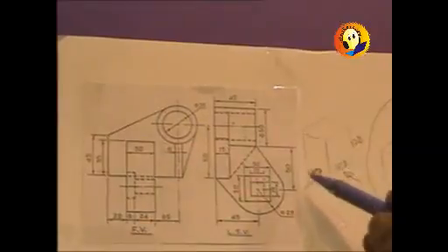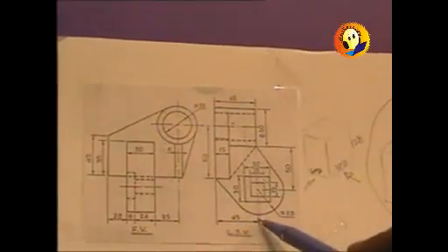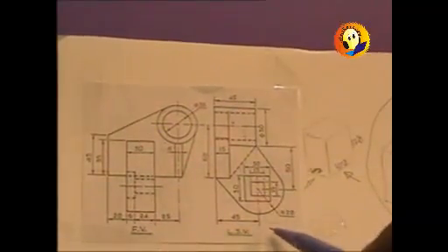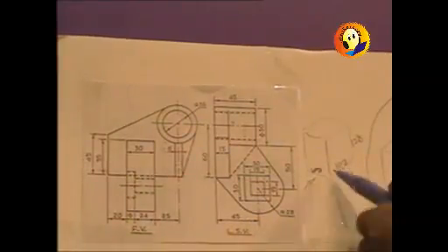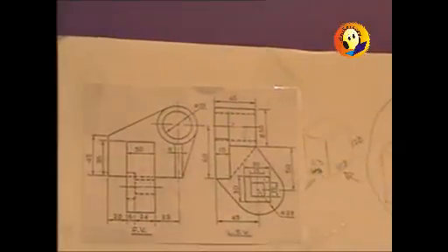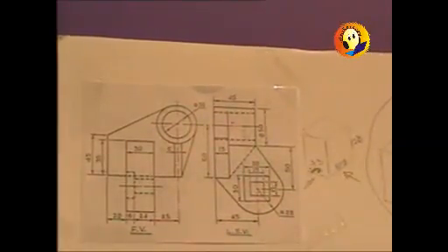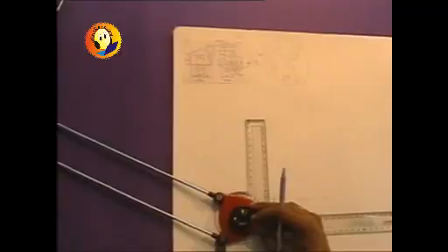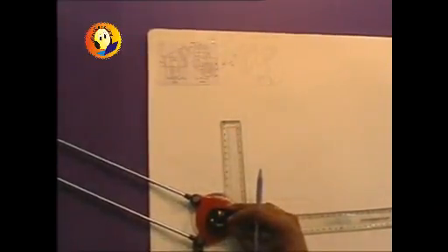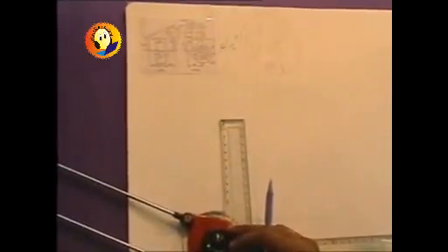And the left hand side view we are required to measure, it is 45 plus the radius 28, that is 45 plus 20, 65, plus 8, it is going to be 73. So let us draw the box of 73 by 100 by 128, and the entire object should be accommodated into it. So we have calculated the overall dimensions, and using those dimensions now we will proceed to draw a box of those dimensions.